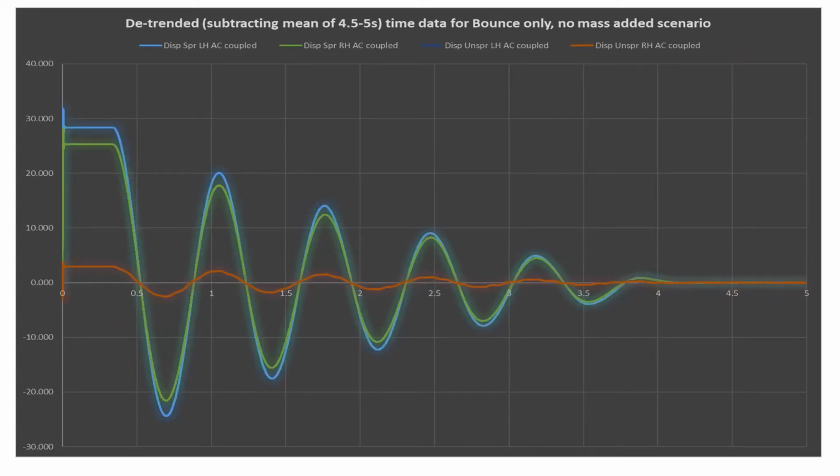Okay, why do we actually need to remove the offset? The answer is that in vibration and in dynamics, we are talking about dynamic systems, and so the offset here represents the static deflection or the static displacement. So basically we don't need those static or DC offsets. And we can simply and readily get rid of those offsets by subtracting from the raw time signals the mean of the signals, for example here, for the signals between 4 to 4.5 seconds or between 4 to 5 seconds.